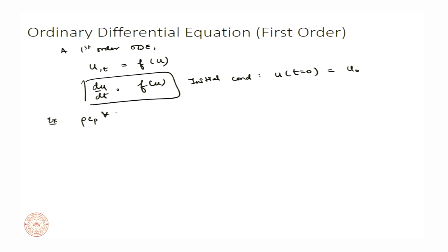Say, a heat transfer problem, which is a lumped body problem. We will come back to this later when we talk about heat transfer, but for now this is our expression, where rho is the density, Cp is the specific heat, V is the volume, dT by dt, in this we do not need partial, we can write complete derivatives, is our temperature derivative with respect to time. h is the convective coefficient, A is the surface area through which convection is happening, T is again the temperature of the body, and T infinity is the ambient temperature.